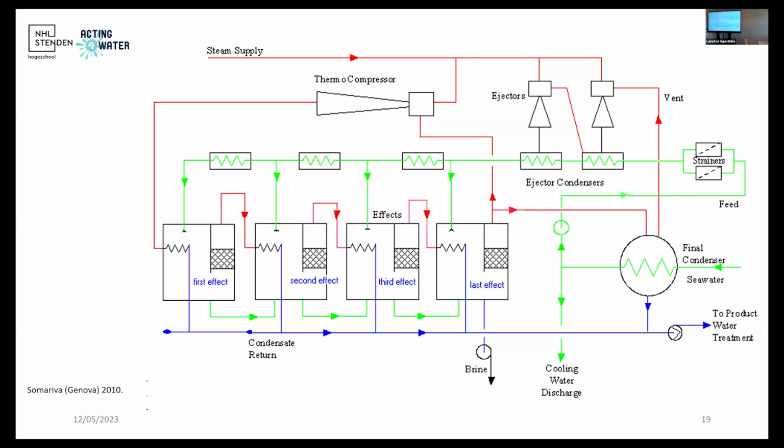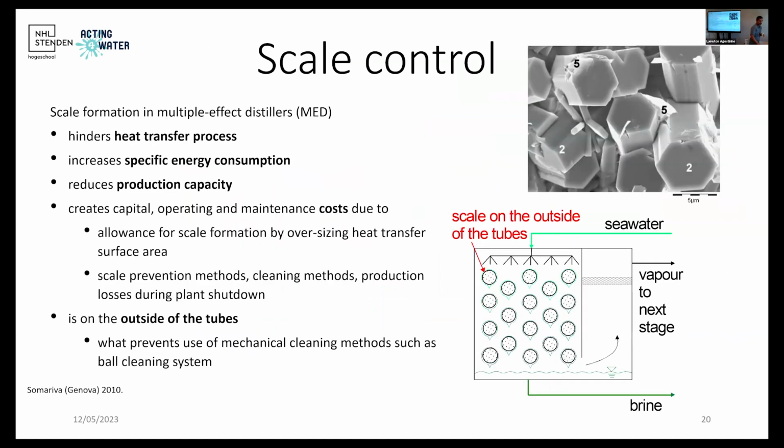pressure recovery pumps as well to guarantee what we call the wet ratio in your tubes, and to avoid, for example, dry spots, meaning basically to guarantee that you have the same flow in all the points, in all the tube bundles, and to overcome the losses that you will have due to pipe length or to other types of valves or systems that will decrease the pressure, for example, from shower number 1 and number 2. So the ejectors are mainly used to keep your wet ratio or to keep your pressure control.